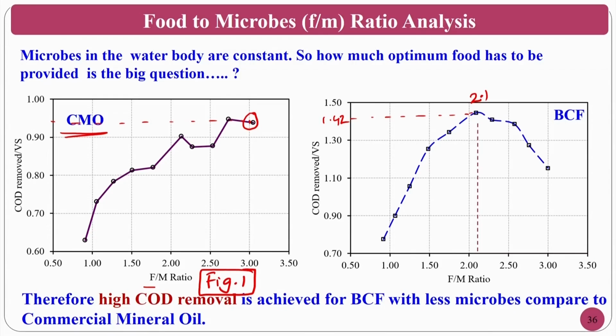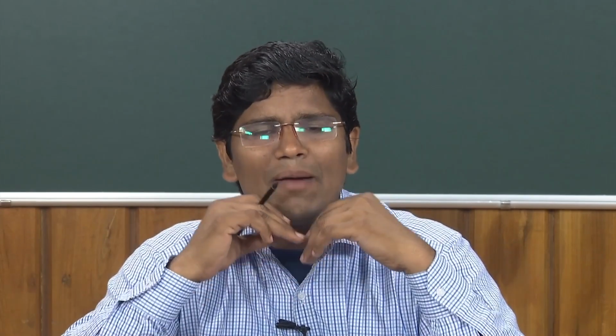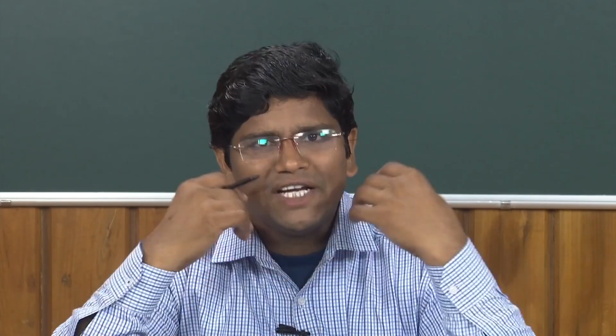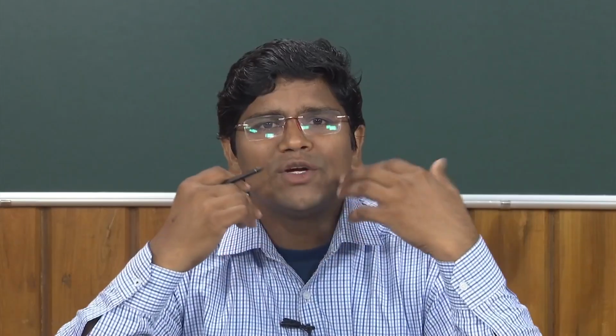What is the inner meaning of this? Assume that I am going to dump this cutting fluid into the river, or into a water body. If microbes are less and food for them is insufficient, still these microorganisms can degrade the biocutting fluid, but not the commercial mineral oil.